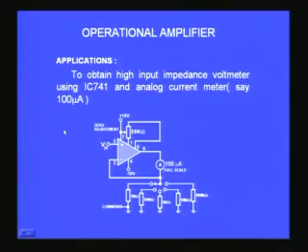Your PCB, your two batteries connected as a dual power supply, everything can be enclosed behind that panel meter, and just take the two leads which correspond to the input leads, and that can become a very good electronic voltmeter. You can have a small band switch connected corresponding to these resistors, so that by switching the resistor you can switch the range of the electronic voltmeter from 0 to 1 millivolt, 0 to 10 millivolt, or 0 to 100 millivolt up to 0 to 10 volts. All will give full scale of 0 to 100 microamperes, and you can construct a very nice electronic voltmeter.